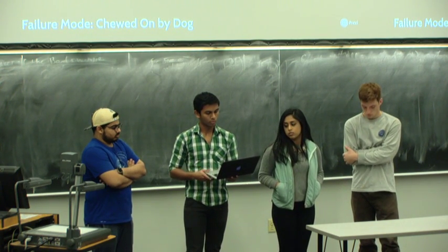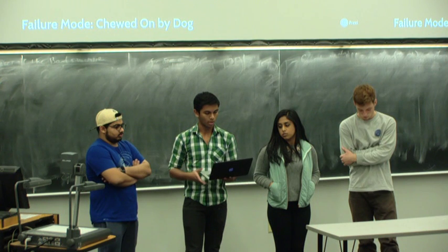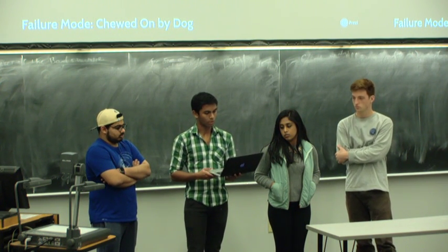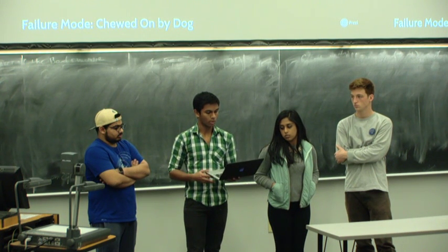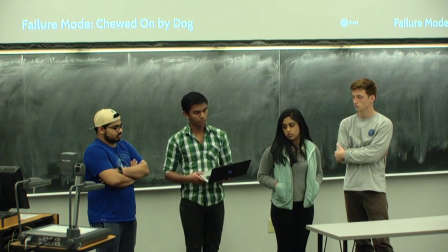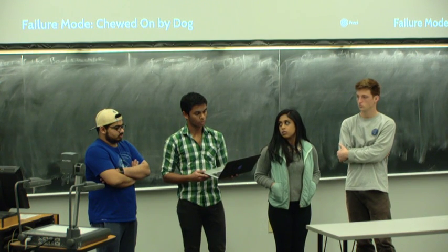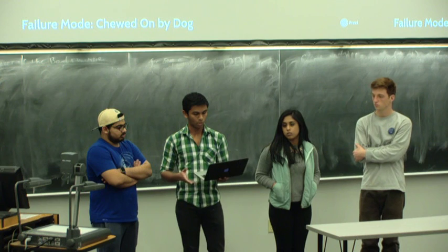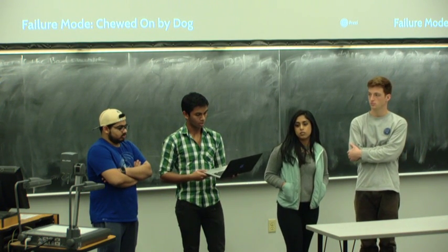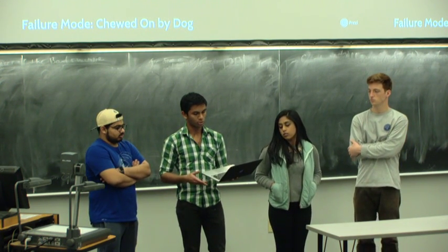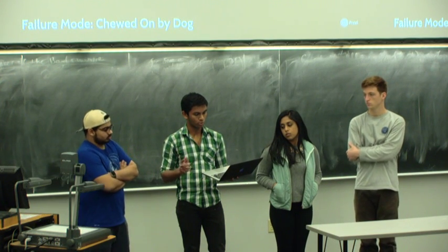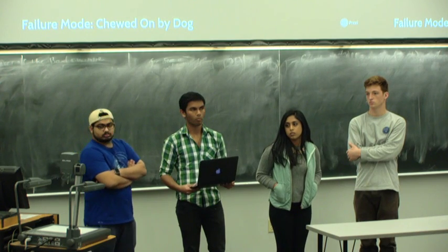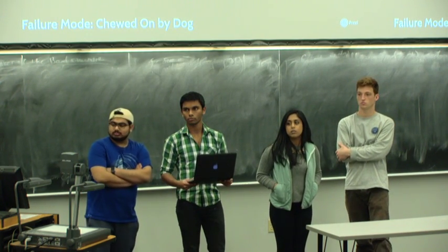The occurrence could be fairly high. It's around a 6. And the current process controls that we had were that the operator training and instructions would take care of that. And the detection was 3. So that gave an RPN of 72, and our recommended action was that we reset the machine every month and calibrate it to make sure that everything is working correctly. And that would end up raising the detection to a 1 and giving an RPN of 24. Very good.